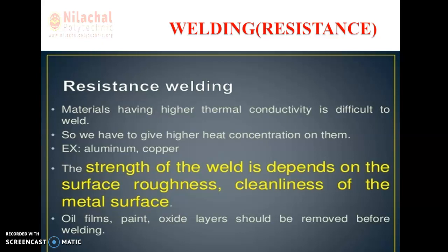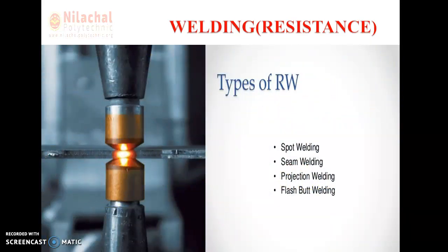Here in the last point it is clearly mentioned: oil, films, paints, and oxide layers should be removed before welding. So before starting the welding process, you have to clean all these things. Thereafter you can go through the welding process.